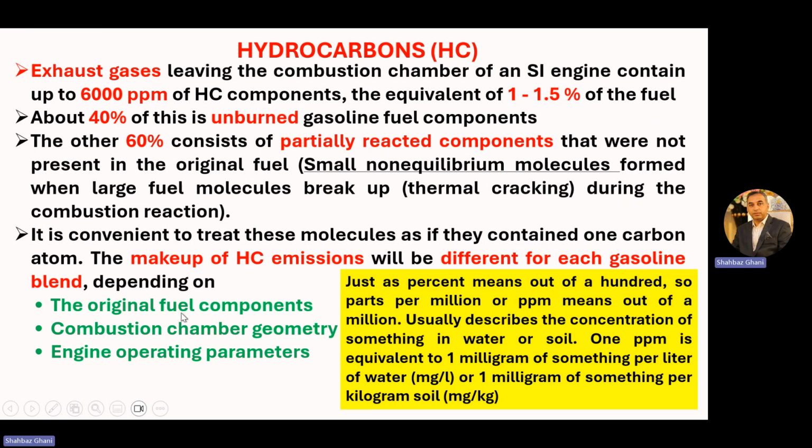The original fuel components are hydrocarbons in different shapes. The combustion chamber geometry is also very important, for example the shape of the piston head and of the block from the top in the center. All these things matter. Then there are the engine operating characteristics or parameters, whether the engine is operating at wide open throttle or part open throttle, or with a supercharger or turbocharger. All these lead to different types of hydrocarbon emissions.